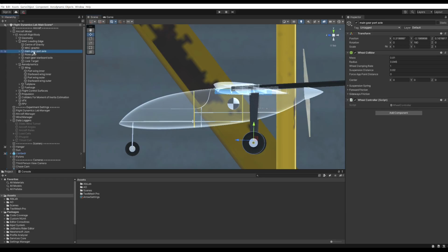One thing you'll notice in a later video, the distance of the wheel axles is slightly different. It's been upgraded since last year as we got some new undercarriage, so just check the actual location of the Z distance of the undercarriage when you're doing your balance to work out where the CG is.